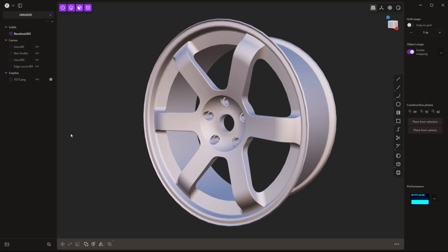We can do that on the fly with Plasticity, but just keep in mind that there is no true parametric sort of relationship between the curves that we create. Once the geometry is created, it doesn't care what you do with those curves. Delete them, move them, scale them, make other variations. So it's really quick workflow, but it is something that you do need to be prepared for if you are trying to model things that are precise or accurate.